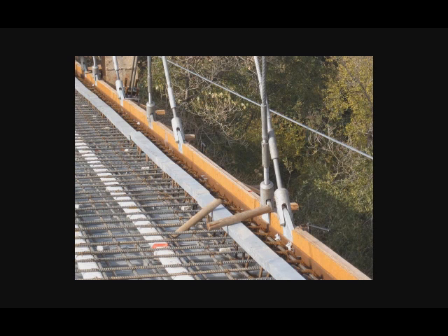So that is one approach where we have the stringers and the deck separate for the tie girder. The other extreme is shown here. This is the Happy Hollow Bridge. If you remember, that's the pedestrian bridge in San Jose, California. At the right edge where the cables are attached, there's formwork for the deck, but then you can see just the top of the tie girder. This is a small bridge, so the tie girder is a lot smaller than what we've just seen for Blennerhassett Island. It's just a WT section.